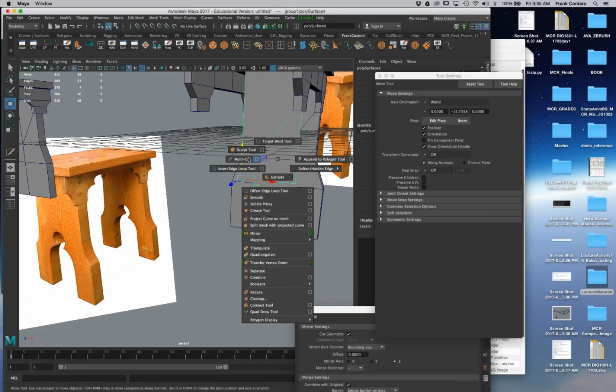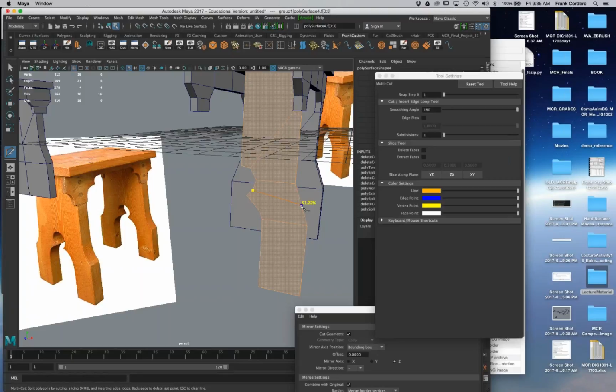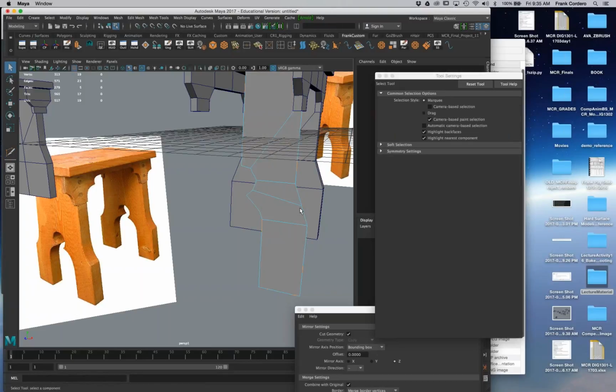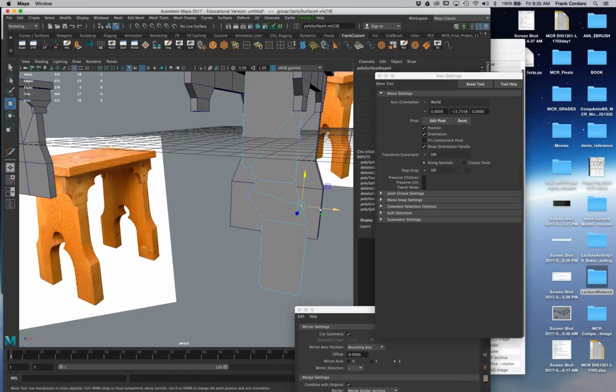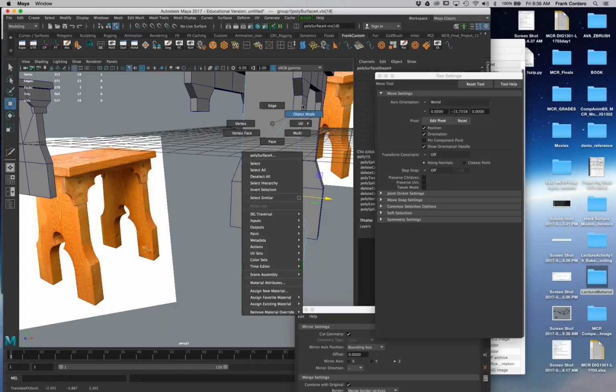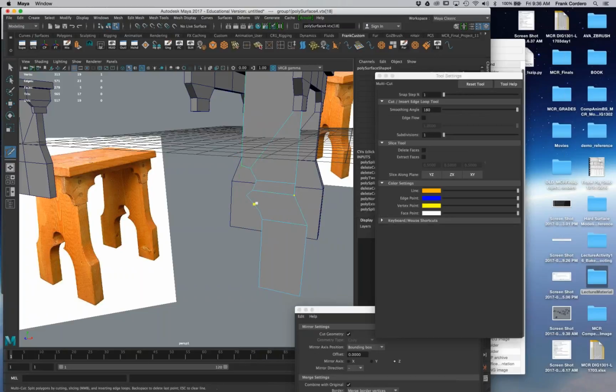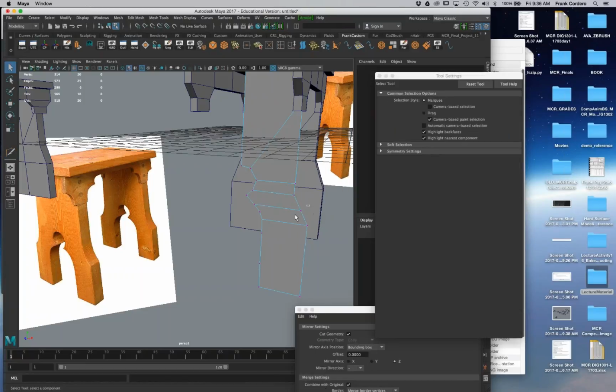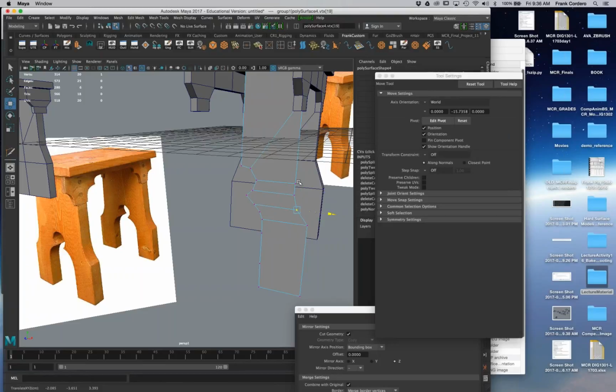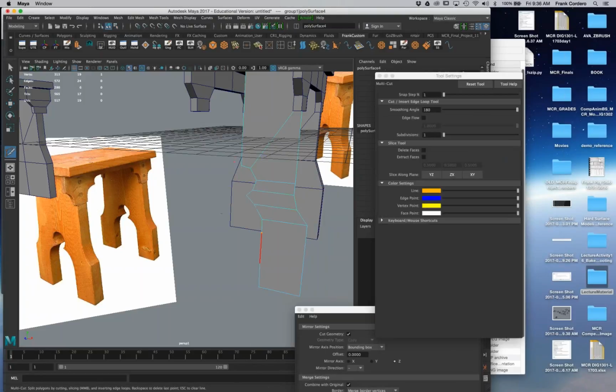All right, so now I'm going to correct for the n-gon. There's an n-gon here. I'll just kind of put that out here, and we're going to need an edge anyway to be able to shape that leg. So I'm going to move that in. You know what? It looks like we might need a few edges to make that a little more gradual. So let's play connect the dots. We'll multi-cut over here, over here. Maybe I'll keep my life a little simple and just make it that kind of a transition. I'll get rid of that one. Again, keeping things simple while I'm blocking things out. There might be one edge I can bring in there because it might be still curving. Cool.